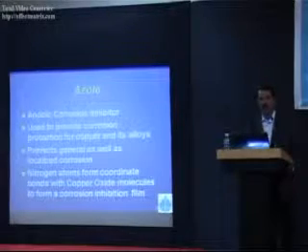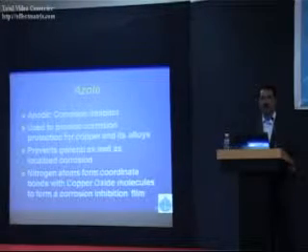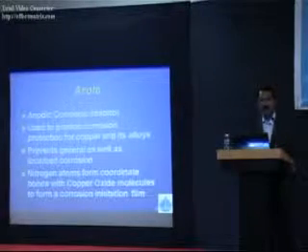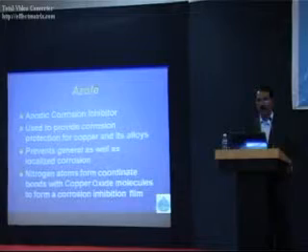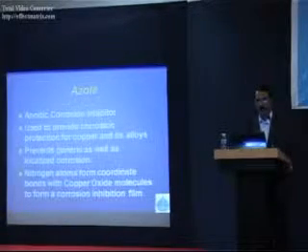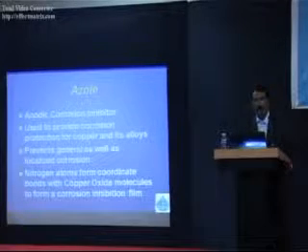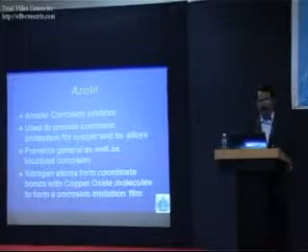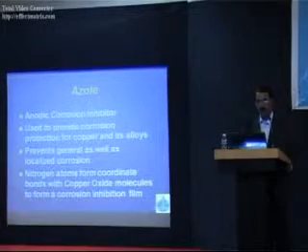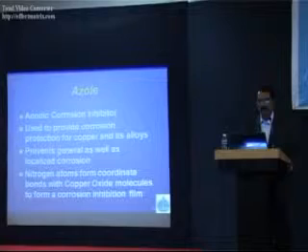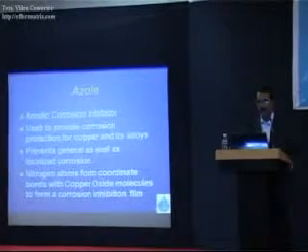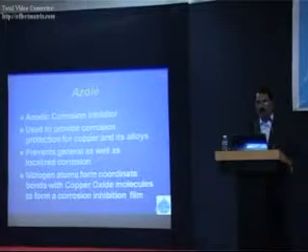Azole is another compound which is primarily used for copper corrosion control. Copper is the major metallurgy in any continuous casting system. Mold is only copper. So azole is a must for any mold cooling system. It provides anodic corrosion inhibition on the copper metallurgy. This is used to provide corrosion protection for copper and its alloys also. It prevents general as well as localized corrosion. And nitrogen atoms form coordinate bonds with copper oxide molecules to form a corrosion inhibition film.